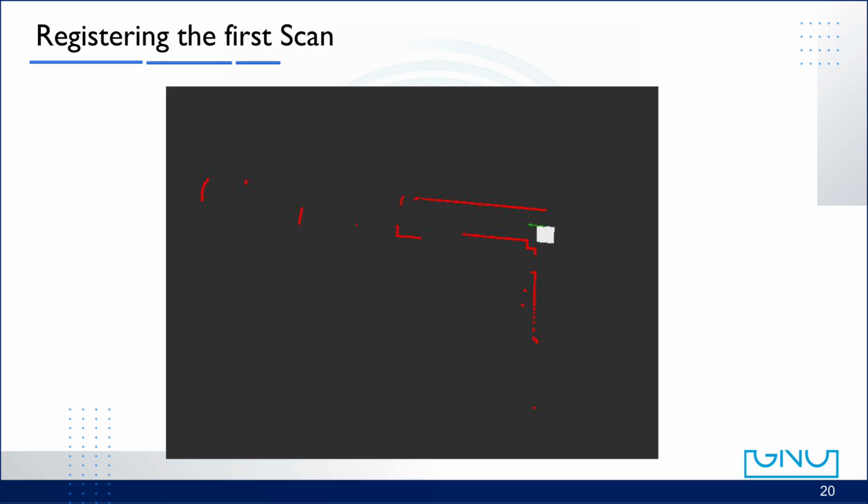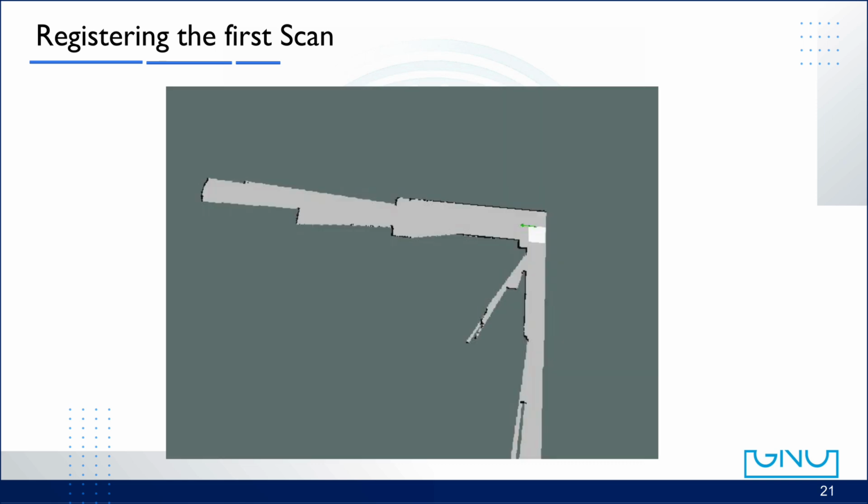For example, if this figure represents the laser scan at the initial moment, the registered map on the right shows how those LiDAR hits create the very first structure of the environment. This initial scan becomes the foundation on top of which all future updates will be added. The initial map is updated directly by applying the log odds for both occupied and free cells.